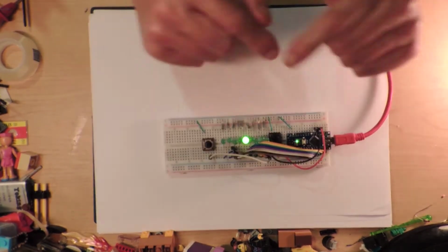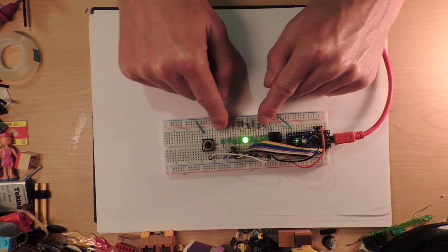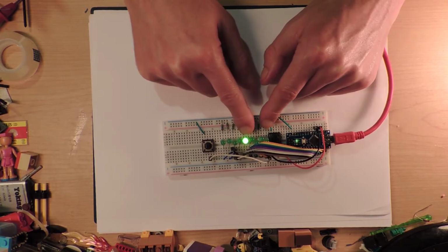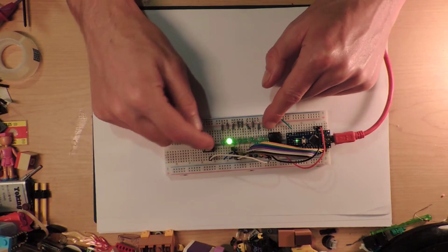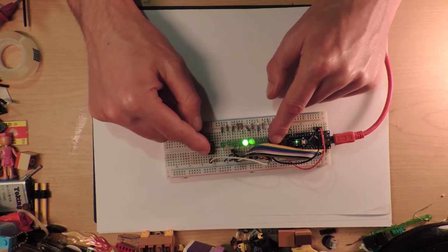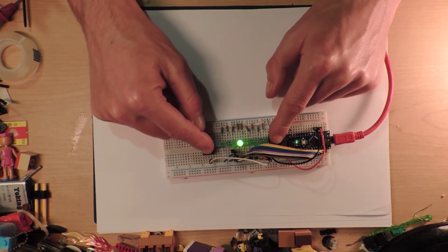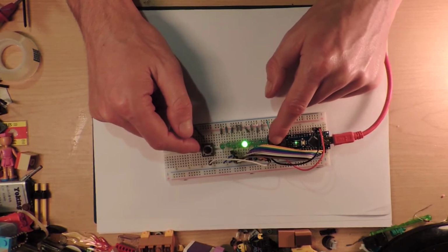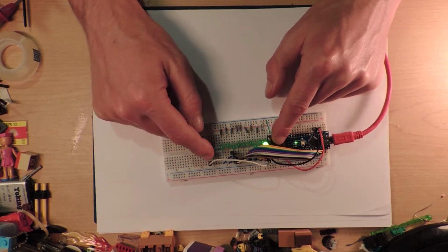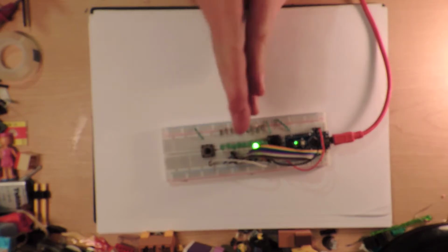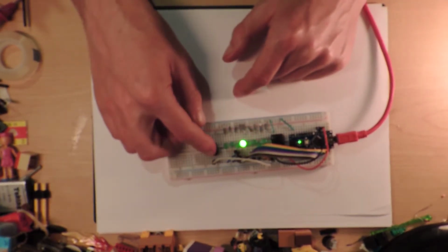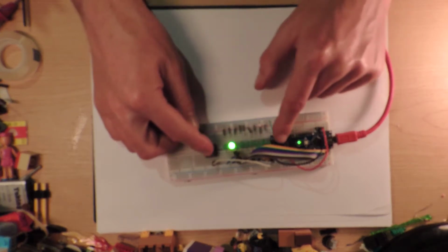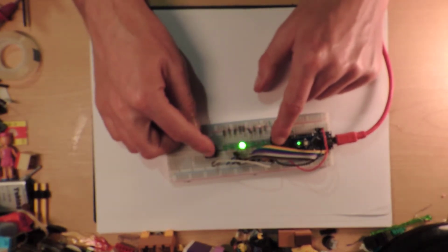It starts off, in this case I've got 9 LEDs, so it's slightly different, and it starts off with only one LED lit, and if I press the button, it goes each way. It's not exactly perfect. One press should only move you one LED. So if I press, you can see that's actually not very good. It's a bit bouncy there.